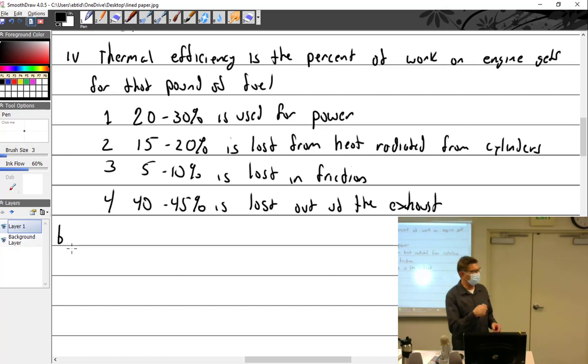There was an air show here in Sacramento somewhere, I forget where exactly, but Chevron accidentally got a little bit of Jet A into the 100 low lead line. Just a little bit, and they found out about it. You have to put in your N number when you get fuel. It's registered for this reason. So they had to go back and look at all of the N numbers that truck filled, and they called them up and said, hi, we're from Chevron, you get a new engine. I did a lot of antique engines that you just couldn't get from the factory. I did probably at least a dozen engines off that AD. So yeah, Chevron bought everybody new engines.